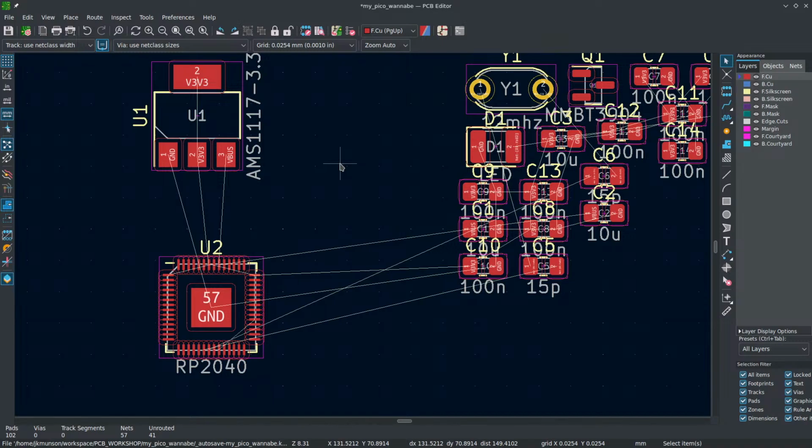Like my very first design, I did all 0402 resistors and capacitors, and I'm telling everybody to do 0805, which has 4 times the area. Those are so impossible to solder, and I didn't understand how hard they were going to be to solder. I got them on, but I don't want to do that again. So it's just all these little things you have to learn by doing your design.